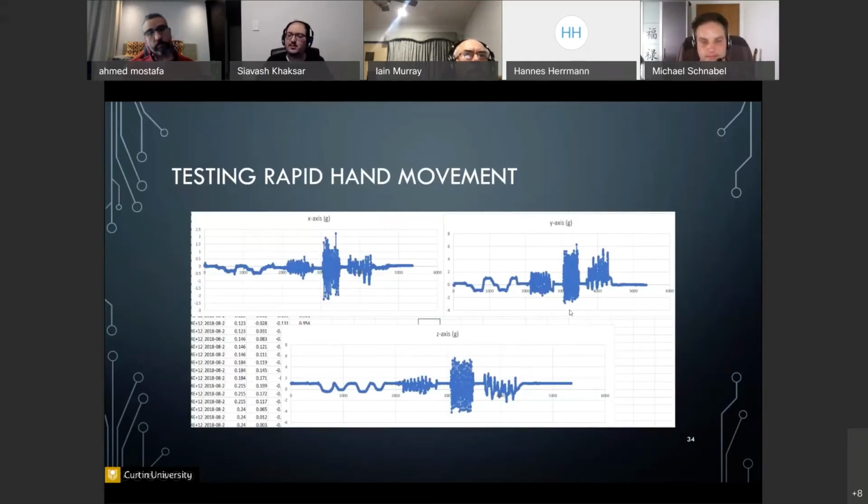This was a small issue we were running into when we captured some data, and when we got it, we saw that there was a cutoff in the data. So when we got the sensors back in, it turned out that the scale that we had set for the accelerometer was set at 2G. But the movement, even a very simple handshake, would have reached above those values. So we had to change the scale back up.